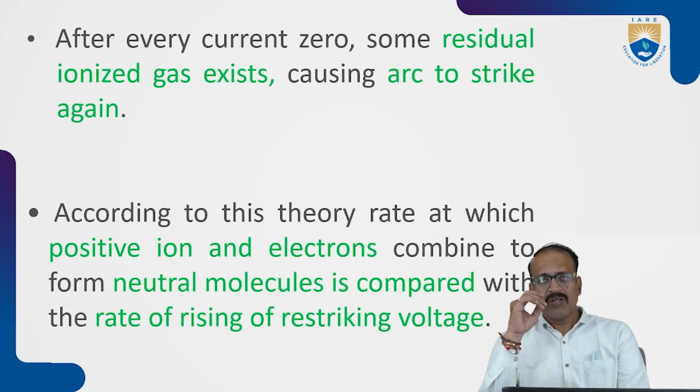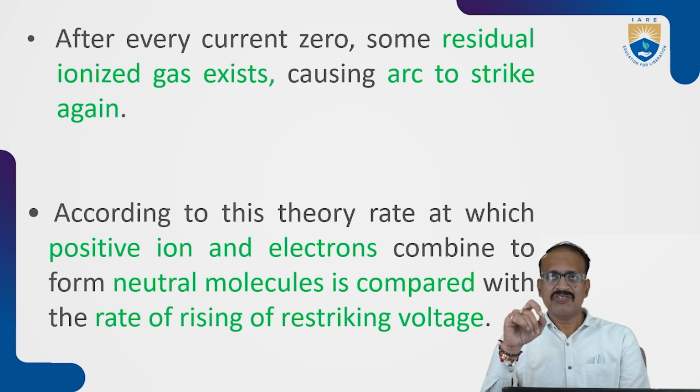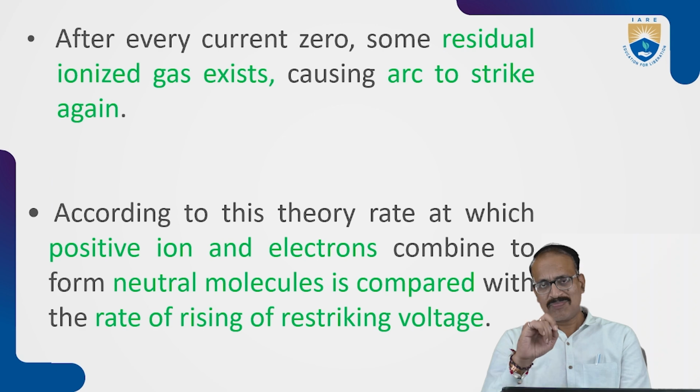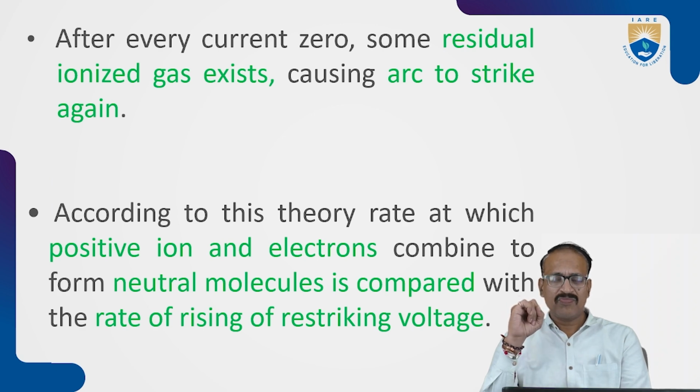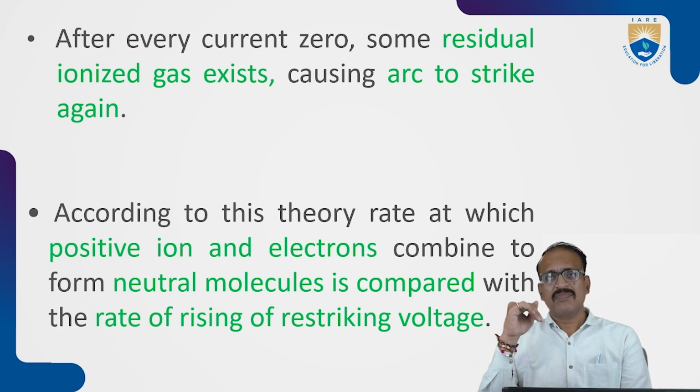Okay. So after every current zero, some residual ionized gas will be there, causing the arc to strike again. So it will support the arc to restrike.